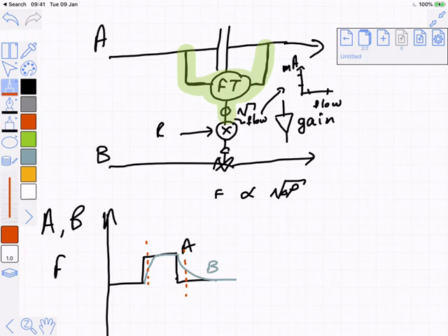What is the solution? Feedback. How do I know that I'm getting the conversion? How do I get the conversion that I want? Not by operating at the temperature Aspen said, or by operating at the pressure that Aspen said, or by operating with the stoichiometric input relations that I calculated using first principles chemistry.